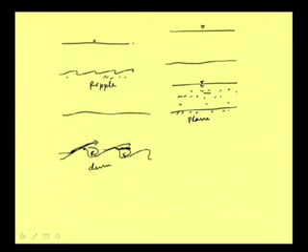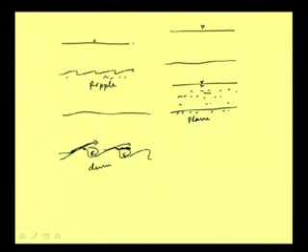And one important point is that this is also a plane bed, and when our bed shear stress is less than the critical shear stress, tau c, there is no sediment motion, and then also we get a plane bed. But the resistance to the flow, the resistance parameter we were discussing earlier, offered by this sort of flow will be much higher, almost double that of the flow when there is no sediment motion.